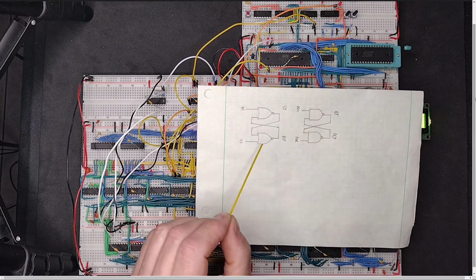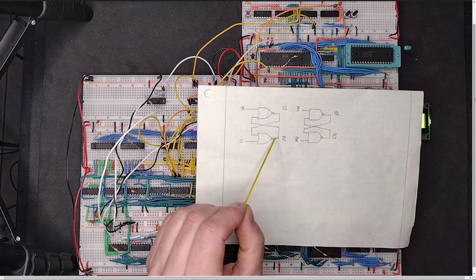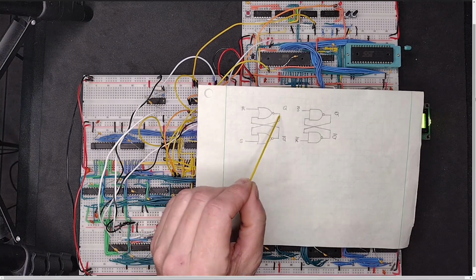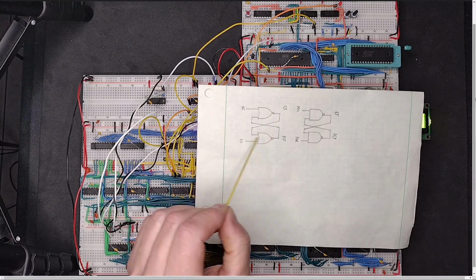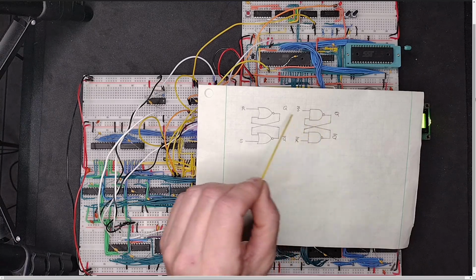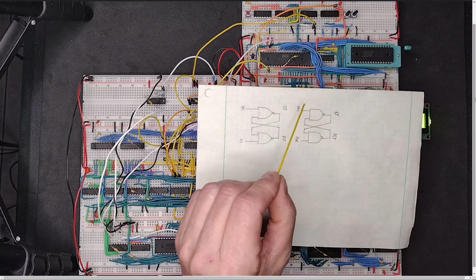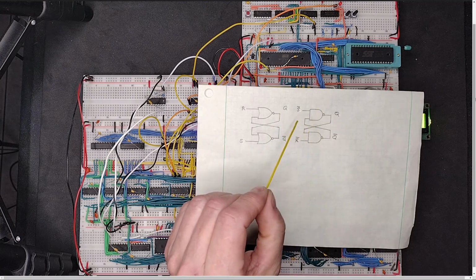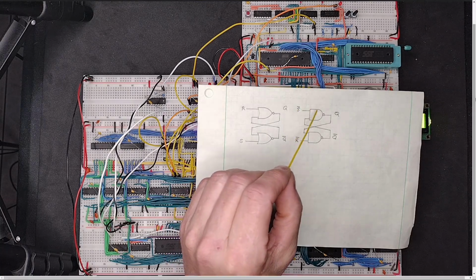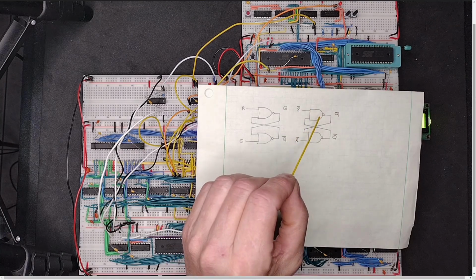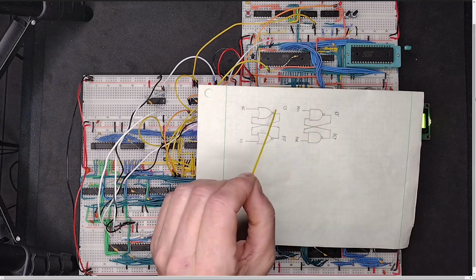You will notice that with the NOR gate, the Q output is on the opposite side from where the set is, and on the NAND gate it's the same. That's related to something I talked about in my last video, about how you can think of an AND gate as an OR gate for negative logic, and this is using that property. So these are like OR gates for negative logic. And if you consider the output negative instead of positive, then you can see that these would be completely symmetric.